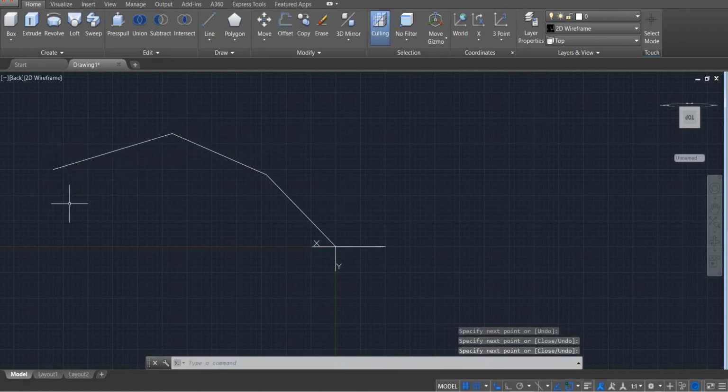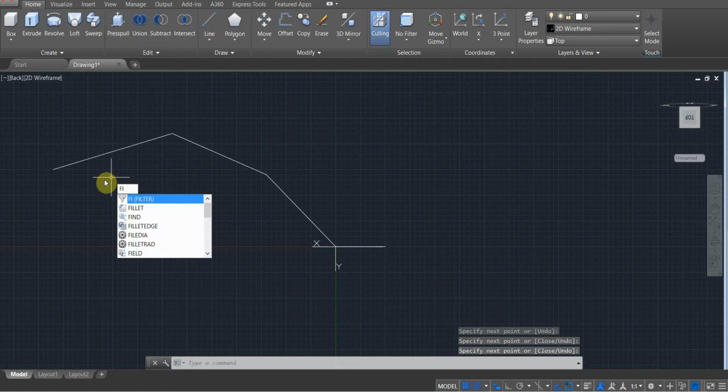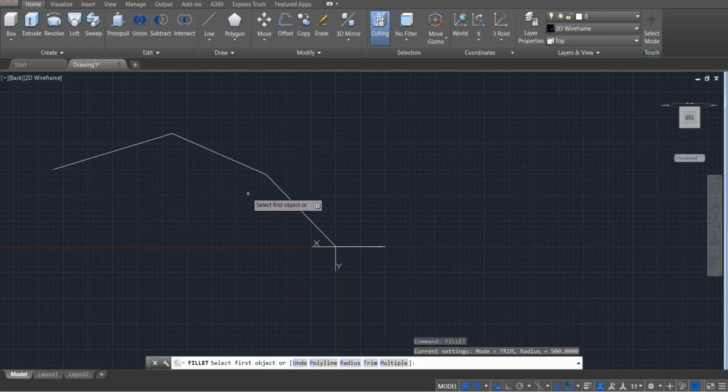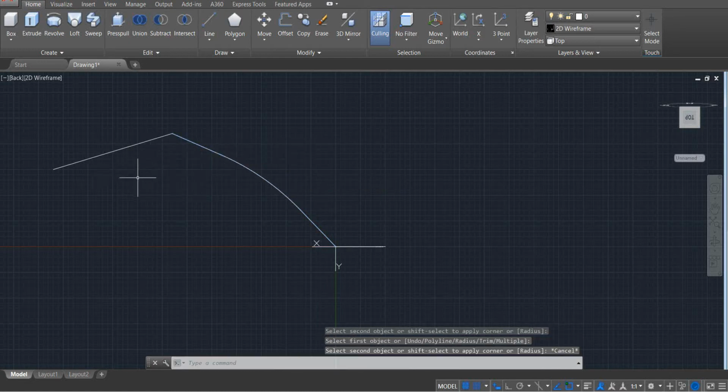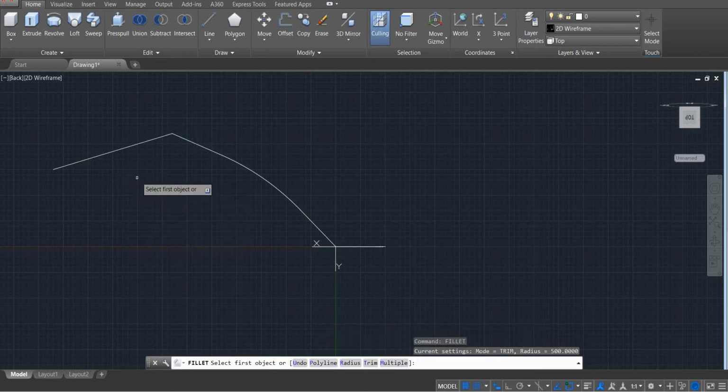So assume that this is the path, and then I'm going to add some fillets here, multiple with the same radius, to make it smooth. Otherwise I might end up with an error, because if there is a sharp corner here, AutoCAD won't be able to give rotation of the section, because the section will be rotated following this path. So try to make it curved. I'm just showing you how we can apply this, but in real applications you should have specific dimensions of this path, so you have to stick to it.